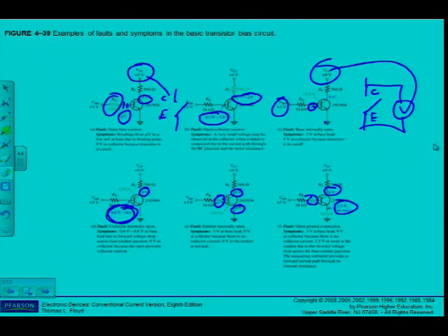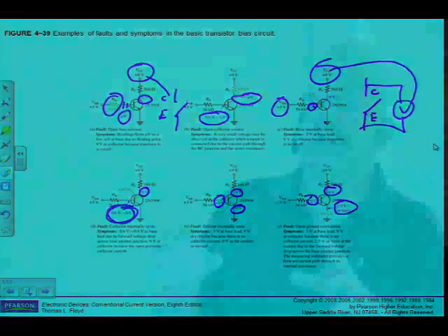But the important thing is that you have to calculate the values as expected for your specific circuit. If the circuit is not working, then at least you know what you have to measure at certain points in your circuit due to current flows, etc., and from that you can deduce what the fault may be.